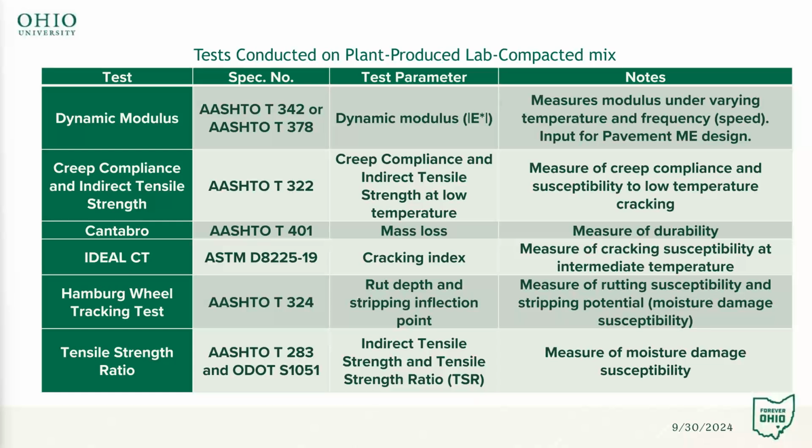So the dynamic modulus measures the modulus at varying temperatures and frequencies. It's a required input for pavement ME design. The creep compliance is a measure of creep and susceptibility to low temperature cracking. Cantabro was a measure of durability.